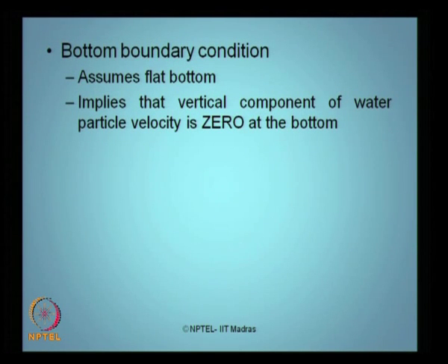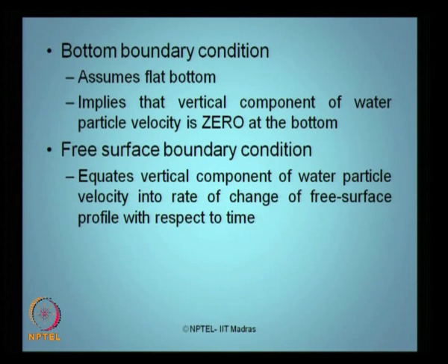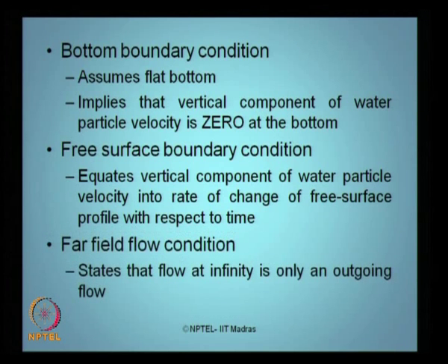If you look at the bottom boundary condition separately, it assumes a flat bottom and it implies the vertical component of the water particle velocity remains 0 at the bottom. If you look at the free surface boundary condition, it equates the vertical component of water particle velocity to the rate of change of the free surface profile with respect to time. When you look at the far field flow condition, it states that the flow at infinity is only an outgoing flow, there is no incoming flow to the system. The velocity derivative is only in the outgoing direction.